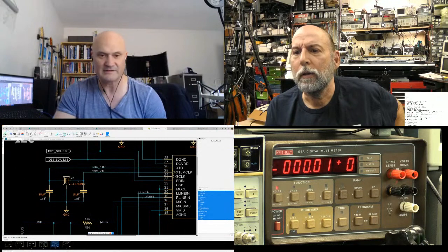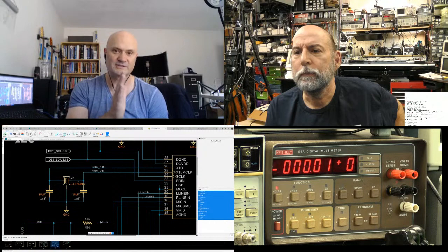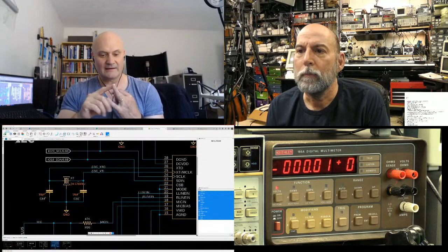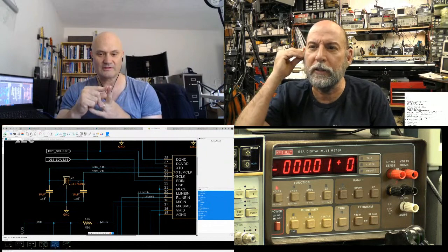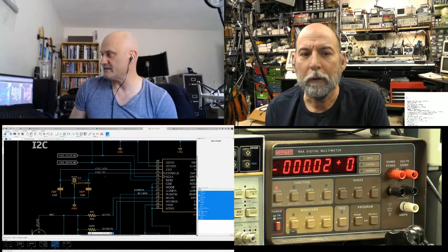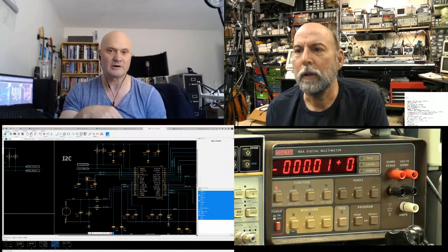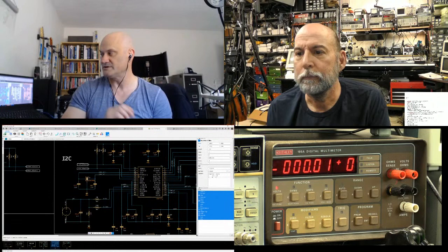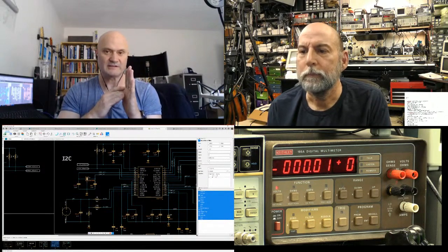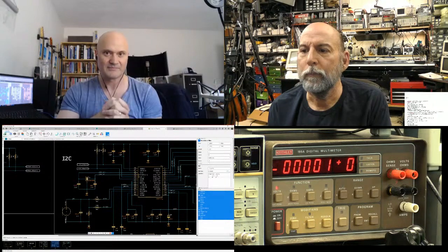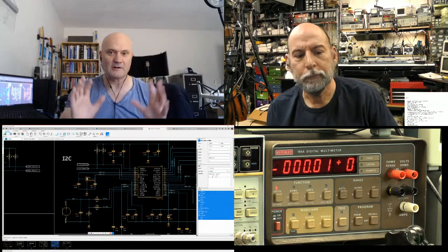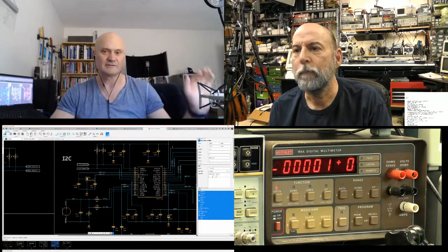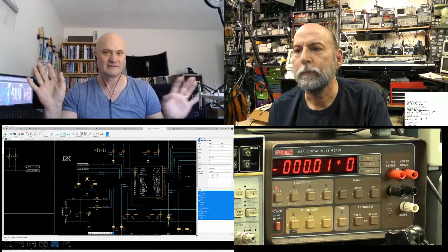And from this 24.576 megahertz crystal, you can derive all the standard audio frequency sample rates, for 8, 11, and so on. They are related to each other. They are synchronized, but the LR clock can be slower on one port, at a different sample rate, but they're edge aligned. They're synchronous to this B clock, which is your master bit clock for the serial transfer on I2S. So it's one clock domain, but multiple clocks. Right. Okay. And a different clock domain is when it's gone through a PLL and it's a completely different frequency that's not synchronous to the source, or it's two separate oscillators. Right.